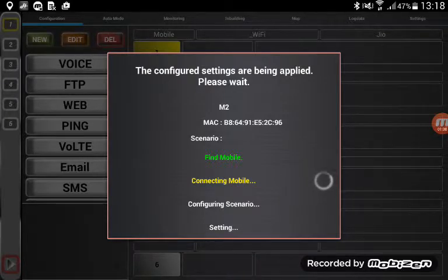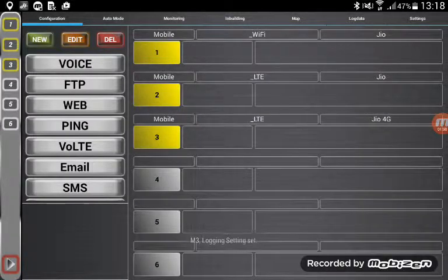Once the phones are connected, we'll need to go to auto mode and download an IBWC file from IBWave Unity server, which is integrated with the XCAL-Harmony server. This file contains all the design data and floor plans and everything else which is required for testing.